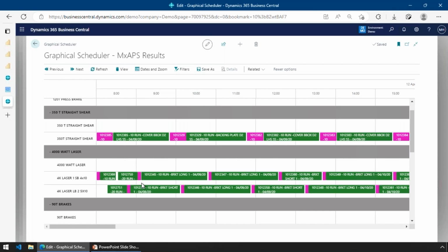Well, I can have two setup segments for that, one for color, one for mold. And I can set it up so that I use that same mold for 10 different colors, and I only deal with the color changeover until I need to run a new part, and then I do the mold changeover as well. So I can reduce the setup at multiple stages. All right, anyway, back to the laser cutter here.